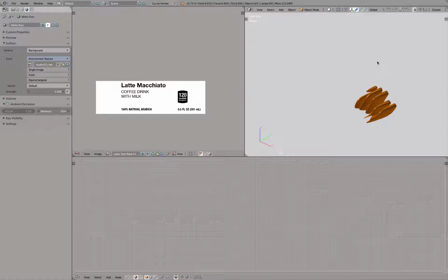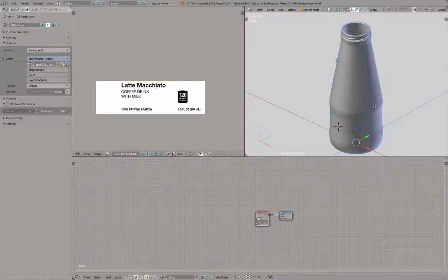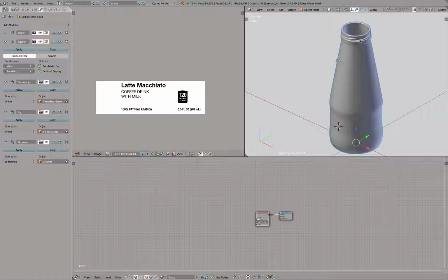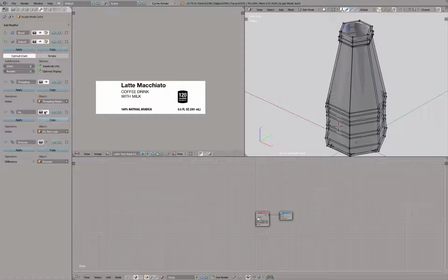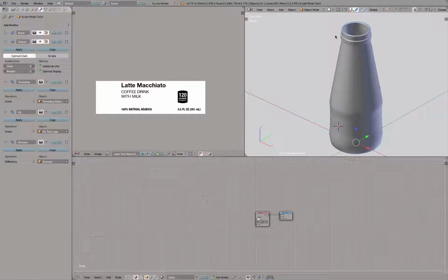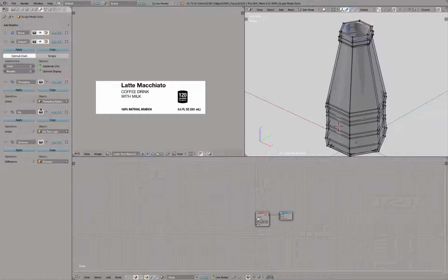So how do we solve this? This is actually insanely easy. All we need is just a clone. So this object here for the moment, I will turn off all those modifiers. And an easy and fast way to turn off all modifiers is simply go into edit mode, Tab, because when you're in object mode and you turn one modifier off, all the others will be calculated. And in edit mode, those modifiers will not be calculated. So I can quickly turn them all off.